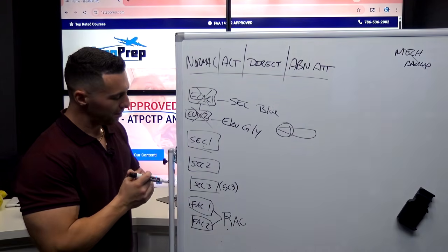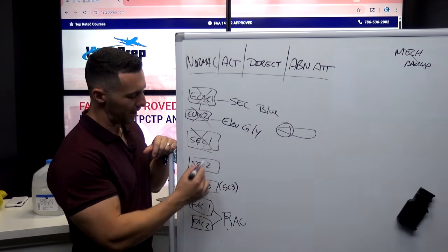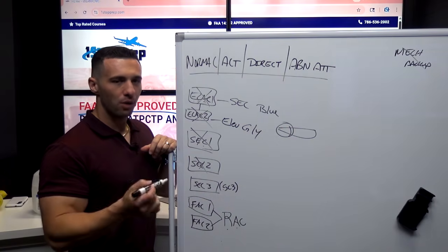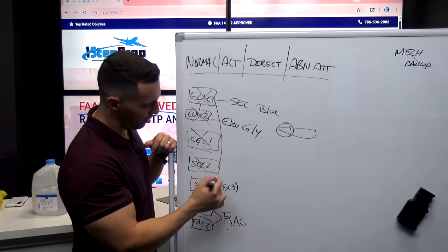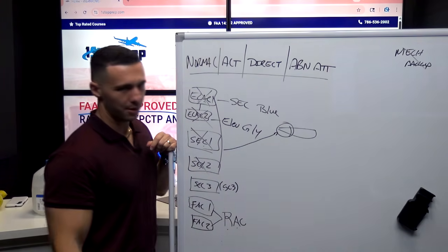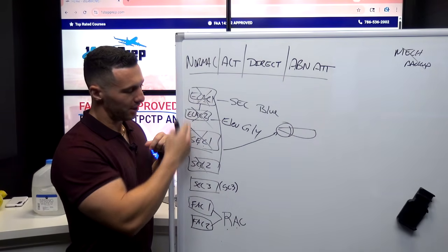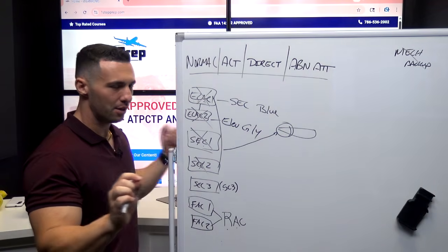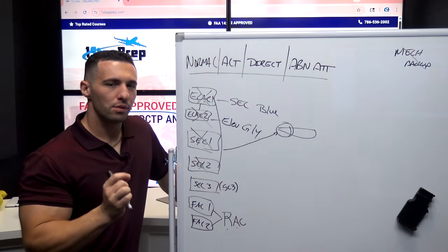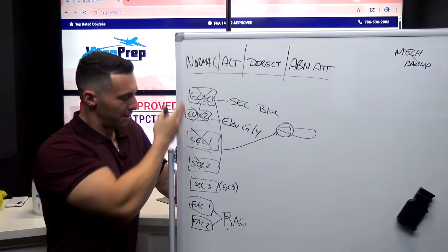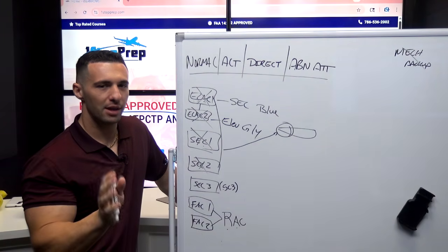So now the question is, what happens if I lose these two? So I lose SEC 1, spoiler elevator control computer 1, and number 2. I have lost all 4 computers that have authority in the elevator. ELAC 1, 2, SEC 1 and 2 control the elevator. If I lose, here's the point, don't miss this one here, pitch control via the elevator, which would be these computers, I will end up in mechanical backup. This is how you get to mechanical backup.